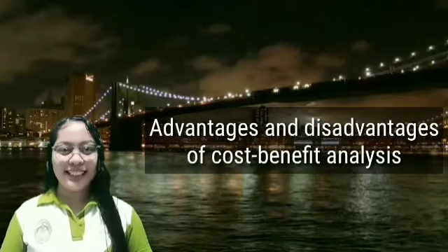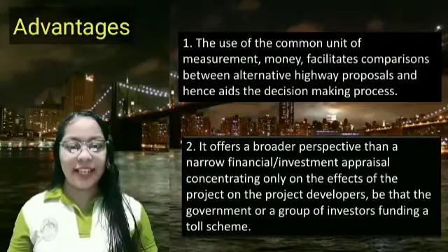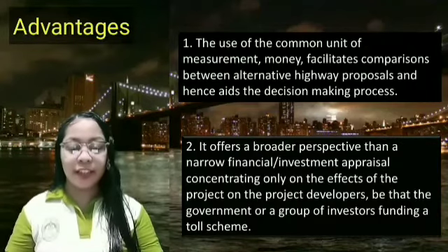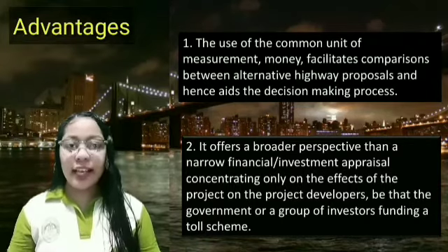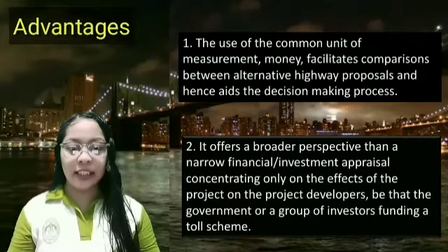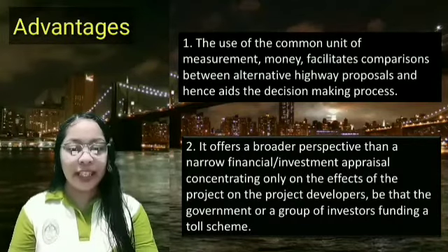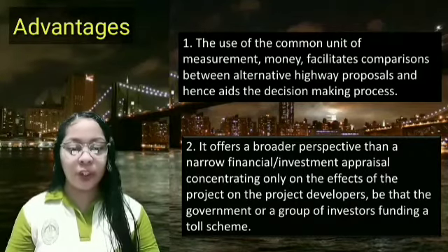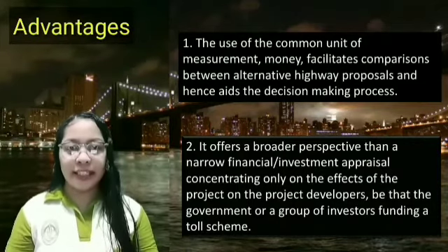The advantages and disadvantages of cost-benefit analysis. First advantage is that the use of common unit of measurement, money, facilitates comparisons between alternative highway projects and hence aids the decision-making processes. Second is that given that the focus of the method is on benefits and costs of the highway in question to the community as a whole, it offers a broader perspective than a narrow financial or investment appraisal concentrating only on the effects of the project on the project developers, be that the government or a group of investors funding a toll scheme.